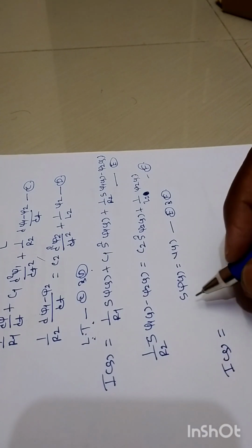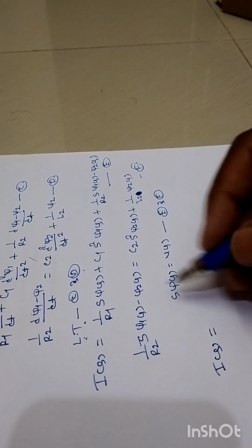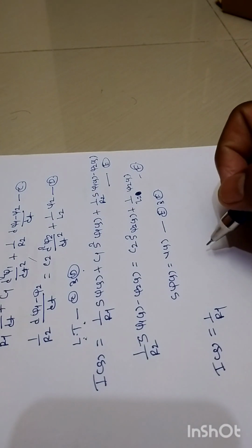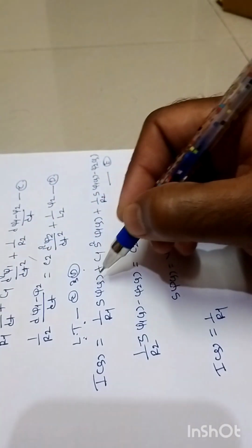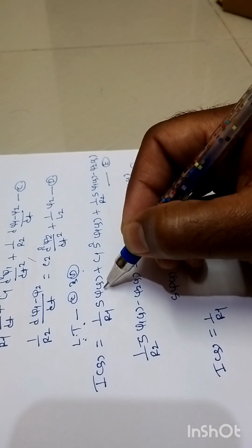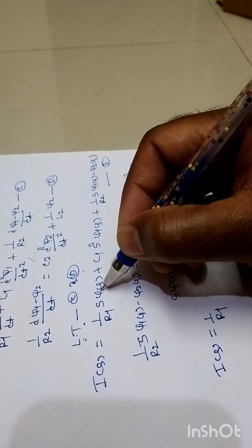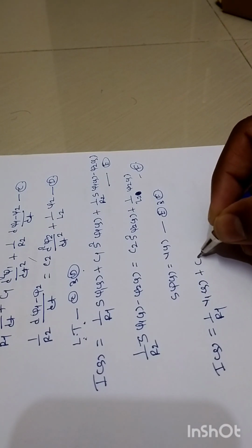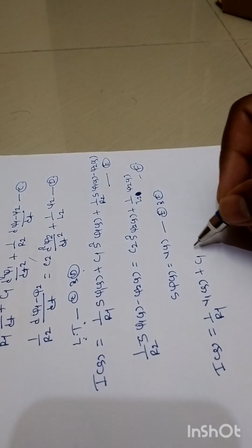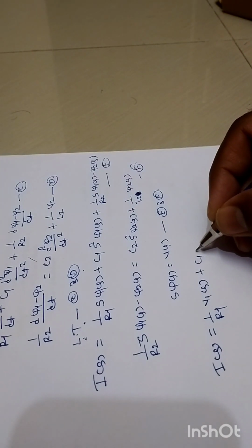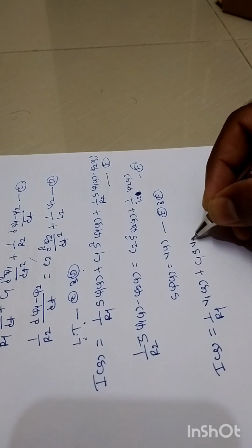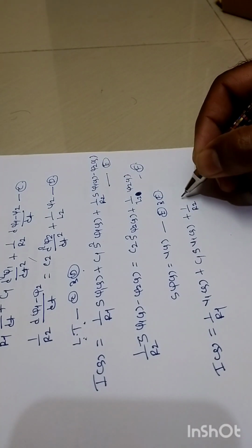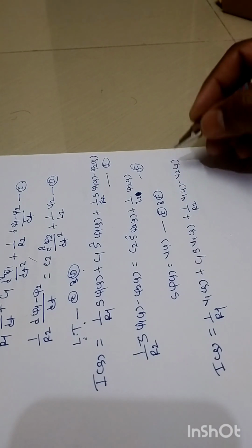First we will consider equation number capital E. It is written for I of S equals to 1 over R1, with this S into psi of S replaced by V of S. So it will become 1 over R1 into S into psi 1 of S, and S into psi 1 of S can be replaced by V1 of S, plus C1 times, where the coefficient of C1 is S square into psi 1 of S, with S into psi 1 of S replaced by V1 of S. So it will become C1 times S into V1 of S, plus again S into psi of S, which can be treated as V of S, so it will become 1 over R2 into V1 of S minus V2 of S, right?